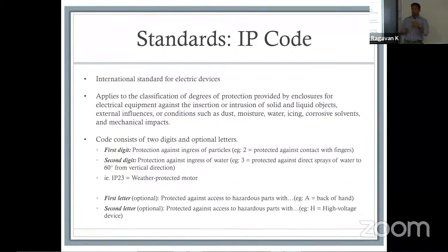Those kinds of requirements dictate how much active space you have for your motor to be designed. If you don't select the right housing, you will end up with insufficient space for your motor design, which will then cause a lot of secondary issues, right?